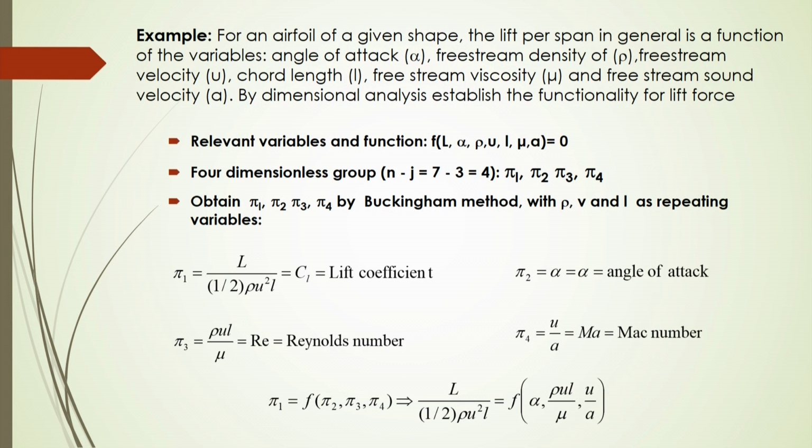Now, by dimensional analysis you have to establish the functionality for the lift force here. We have discussed lift force and drag force in the previous lectures in the module on drag, lift and cavitation. So, in this case we are saying that this lift force will be a function of the angle of attack, free stream fluid density, velocity of the flow, chord length, free stream viscosity, and also the sound velocity there.